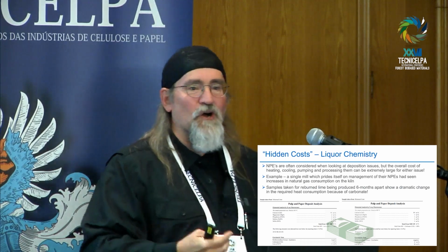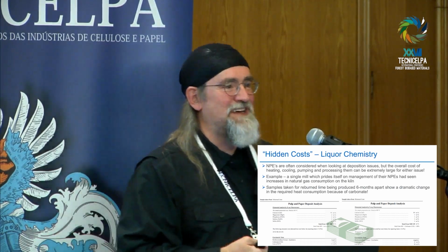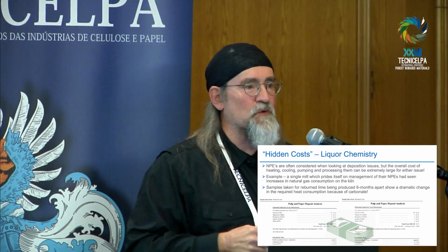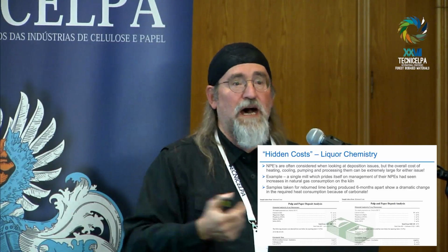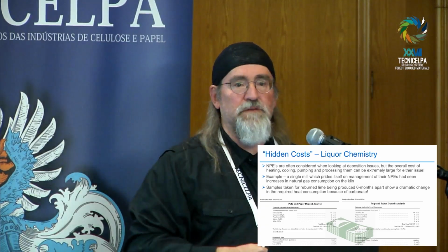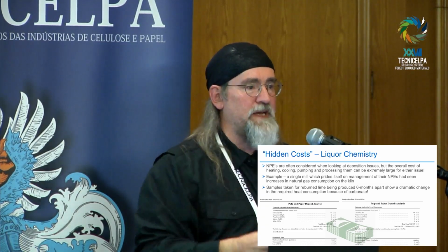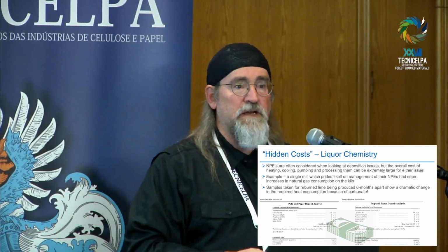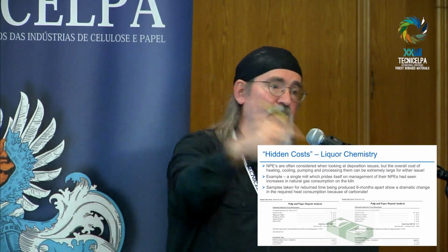Okay? It's not hard to get involved in these projects. It really isn't. You know, I have mills all the time that have pressure filters for white liquor, and their project is to optimize CE. I'm going to raise my CE. I'm going to help myself. Next thing you know, the white liquor filters plug in every day, and they're acid cleaning, and they can't get throughput, and they're adding caustic. And they say, how do we fix this? And I say, put your CE back down where it was.